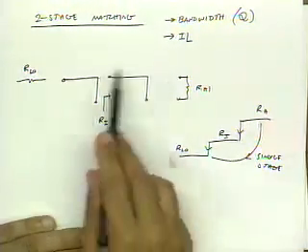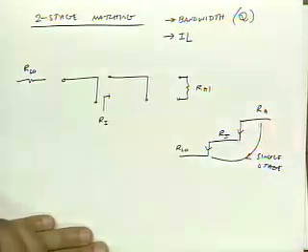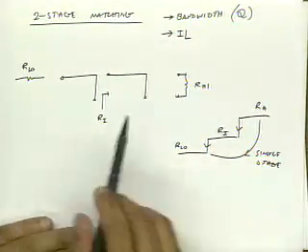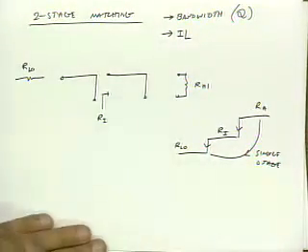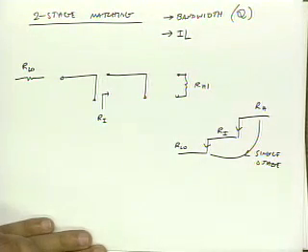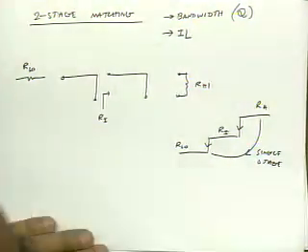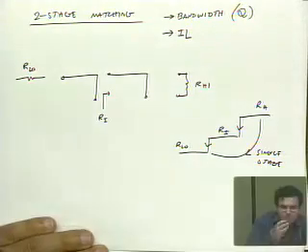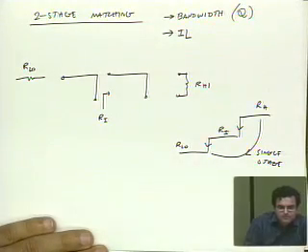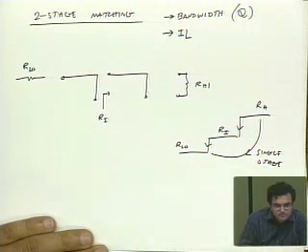Do you think this will have a higher quality factor? Just if you had to guess, would the quality factor of this matching network be higher or lower than a single stage? Someone's guessing higher. Anyone for lower? Lower. Okay, why is it lower? Use the mic, yeah. Right now we don't have to amplify so much in one stage. We can split into two stages. So Q is smaller. That's right.